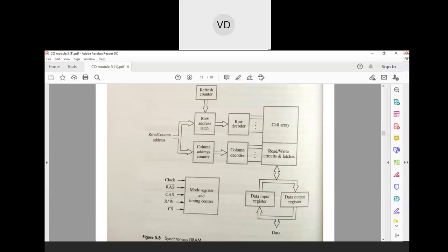Why we are doing this, we have already seen in direct memory access. If we transfer data word by word, then after every transfer of a word, an interrupt signal should be generated. But this will become hectic. To avoid this, we are going for transfer of a complete block. Direct memory access means a direct block of data is transferred from the memory to the processor, or processor to the memory, or including any device. So when the complete block is transferred, then one interrupt is generated. Because of that, we are going for the complete block transfer.